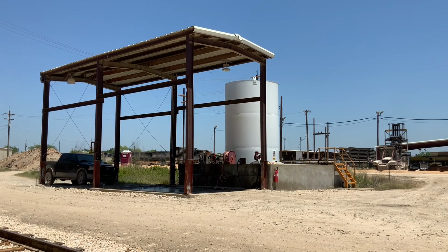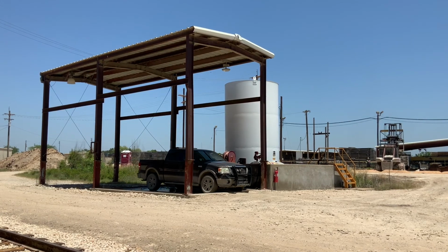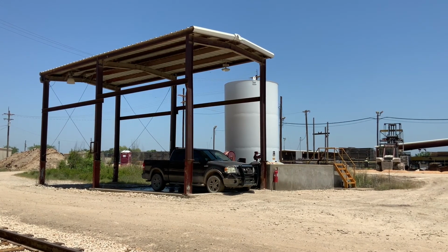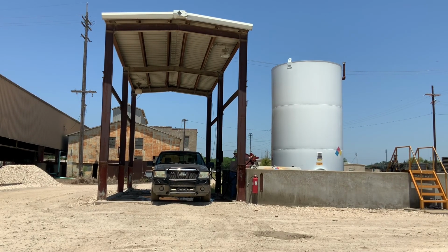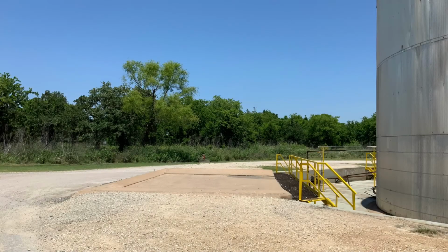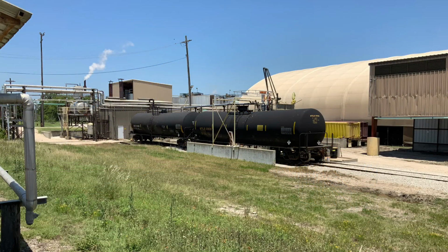When refueling mobile equipment or yard vehicles, always drive your vehicle into the secondary containment. This containment will catch any spills of diesel or gasoline that may occur during fueling. Tanker trucks and other bulk transportation vehicles should always be unloaded in containment. All tank cars are unloaded at the oil unloading rack where there is adequate secondary containment.